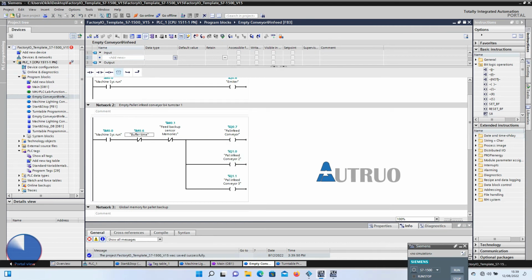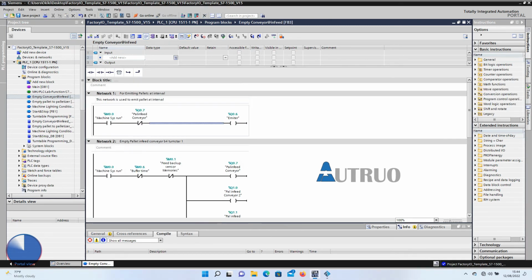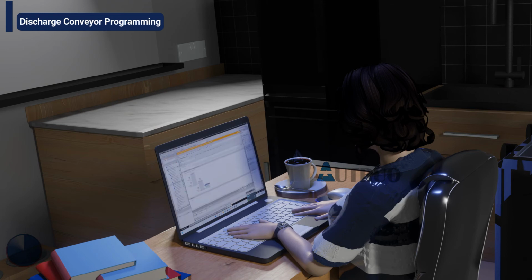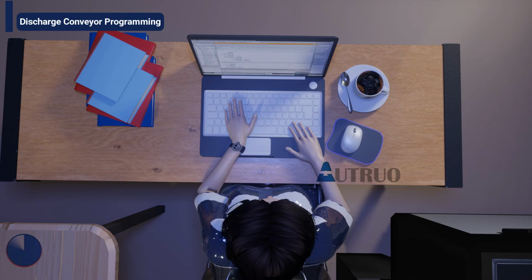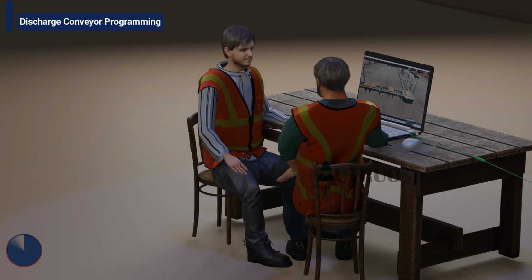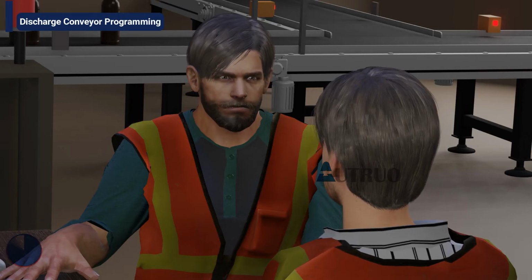Again, we also intend to control how the pallet will be emitted. So we'll put one of the conveyor contacts at the emitter rung. Now when the conveyor stops, the pallet will stop emitting as well. I see. The in-feed conveyor becomes active as soon as the forward conveyor rotates. Perfect. Those additional contacts solve the problem. So when the conveyor stops, the emitter also stops emitting pallets.